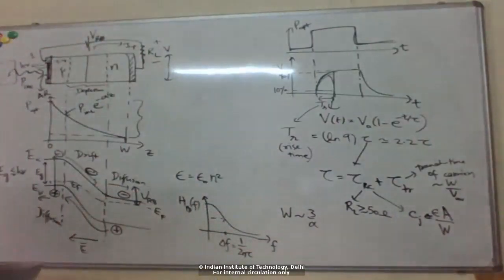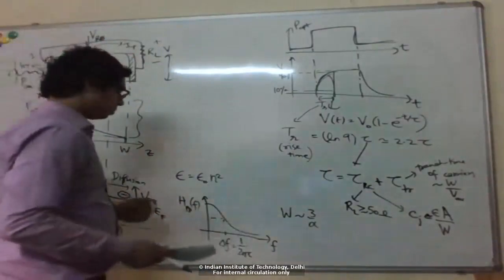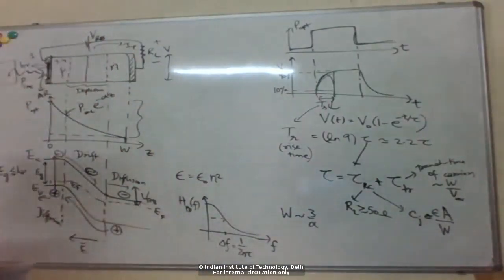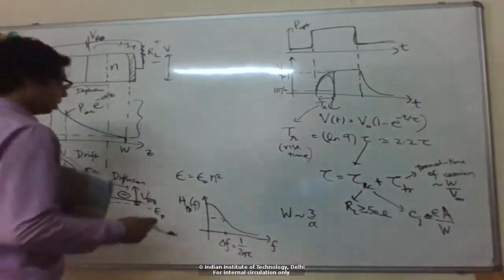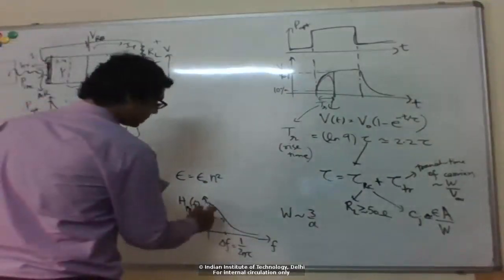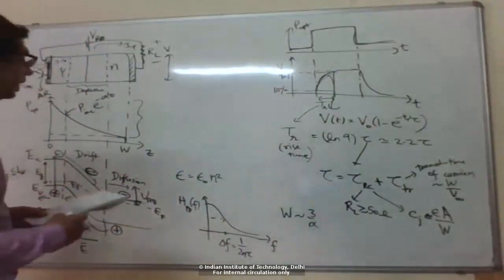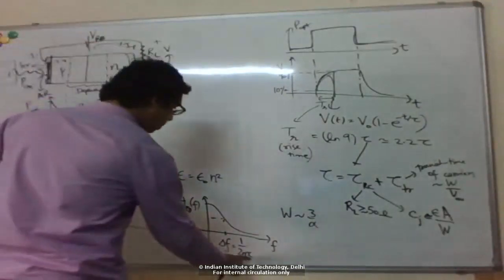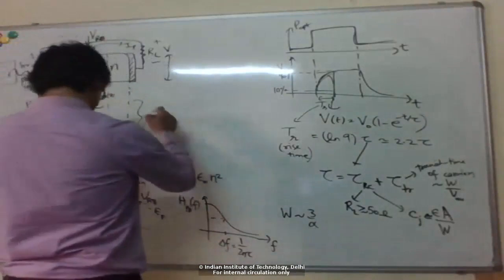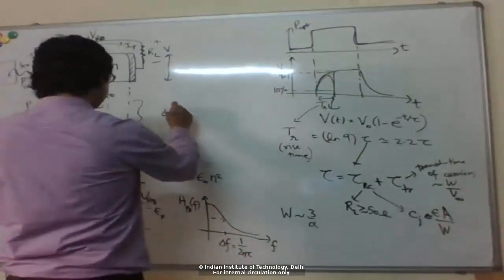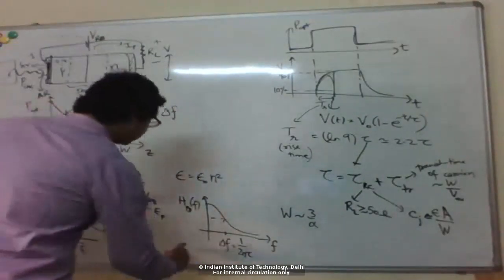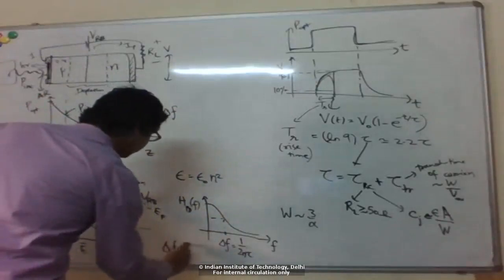Which is sort of what we do for modern telecom systems. So this delta F has to be larger than the bandwidth of the signal that you're trying to detect, right? So you can see what timescales you need here. So typically this delta F is kept somewhere around the bit rate.